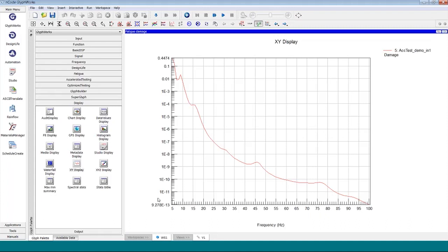As a matter of fact, if you were to go out and continue to run around the proving ground continuously, and you were to monitor the fatigue damage spectrum over time, you'd see that these levels would continue to go up and up in a way that represents the accumulation of fatigue damage, and also in a way that a frequency spectrum, a straight PSD, doesn't. So this is highlighting one of the benefits of looking at this in terms of fatigue damage.